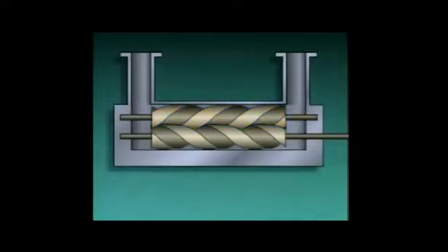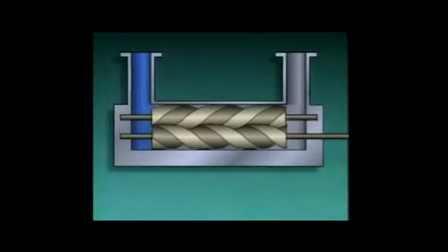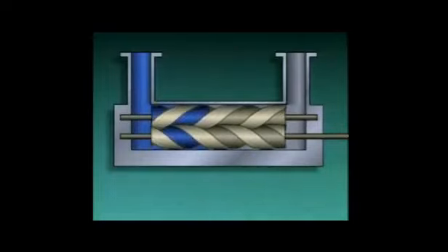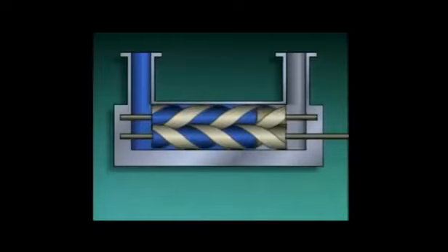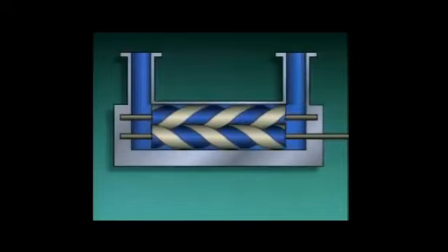During operation, liquid enters the pump through the suction port and is directed to the suction end of the screws. As the screws turn, liquid is trapped in the spaces between the casing and the threads on the screws and moved along the casing until it reaches the discharge port, where it's forced out of the pump.